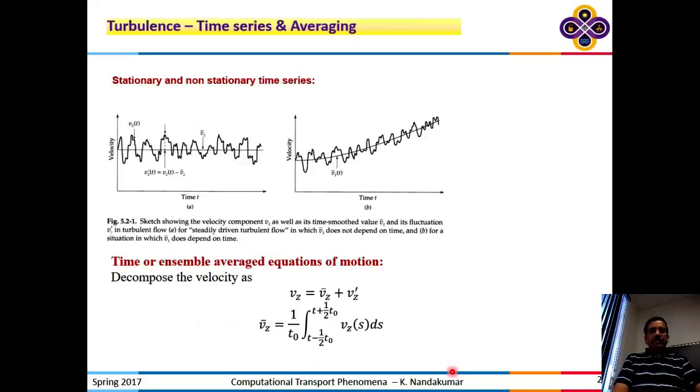So back to turbulent flow. That previous slide essentially gives you the idea of filtering in time or filtering in space to smooth out information and extract the information about the fluctuations into a separate quantity. And that will become clear once we apply it to the Navier-Stokes equation. So we're just defining what that operation is.